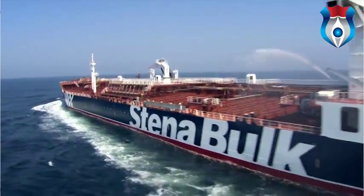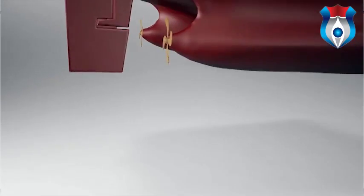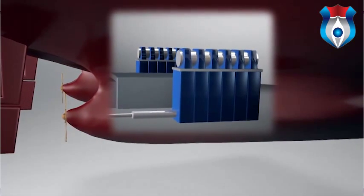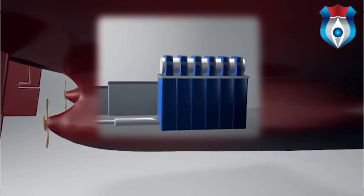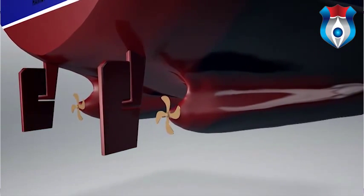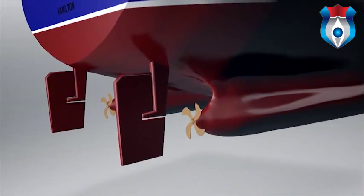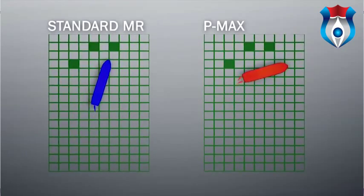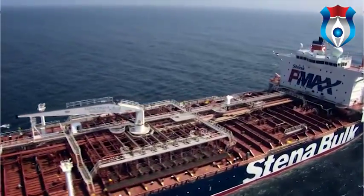The ship has a full double hull, and in addition to this, the vessel has dual operation and control systems. There are 2 engine rooms completely separated by fire and watertight bulkheads. All control systems are redundant, and each engine has its own fuel system. This means that the machinery systems work independently of each other, which is obviously a very big advantage in terms of safety. As the result of the dual propellers, dual rudders, and twin steering gears, the P-Max can make faster and tighter turns than a traditional MR tanker. That is a big advantage in both efficiency and safety.